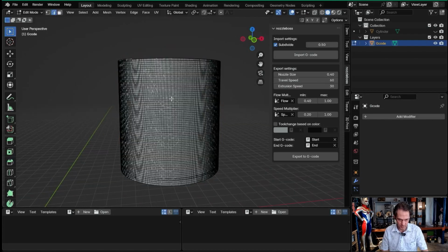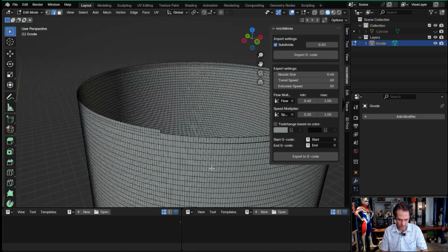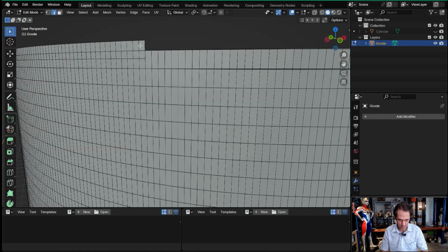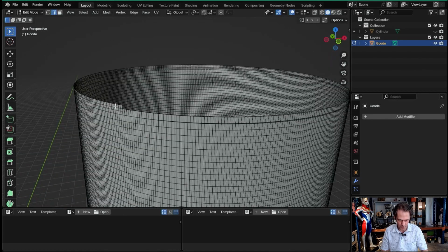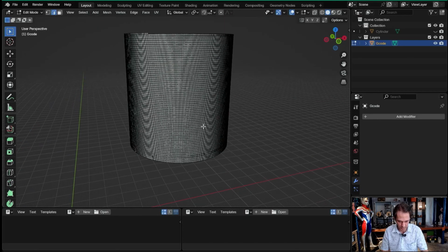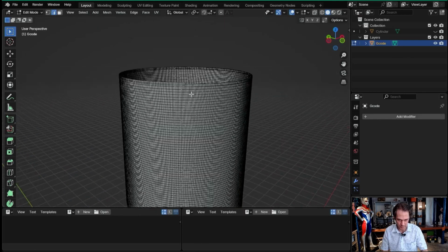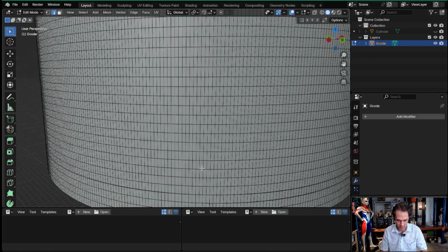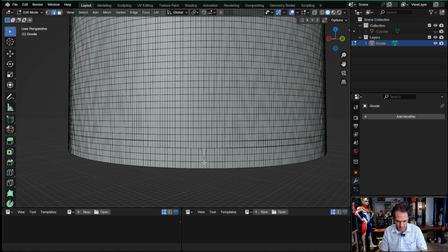There's a little issue I've found with it, that for some reason in vase mode, Cura overlaps the last layer, which is a bit irritating. Maybe it doesn't matter so much when it's printing plastic. When it's printing clay, it tends to make a squishing mess on the top layer. And it also creates this weird thing here where it extrudes too much on the first layer.